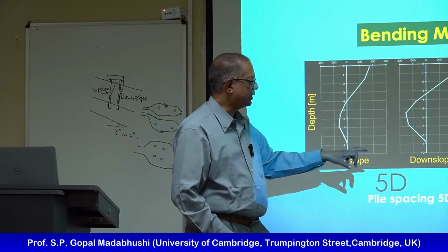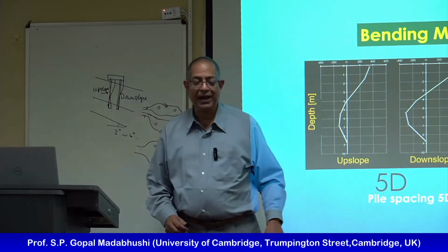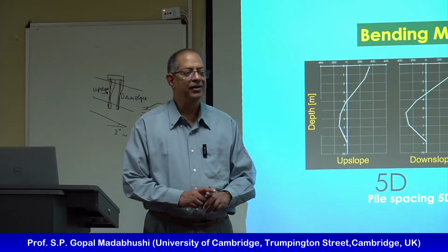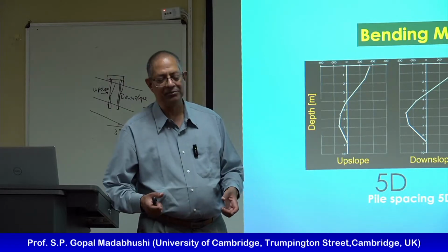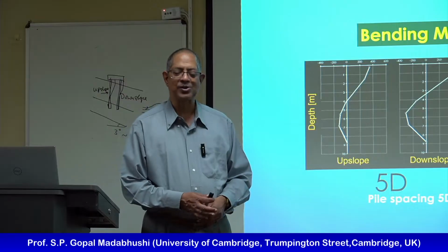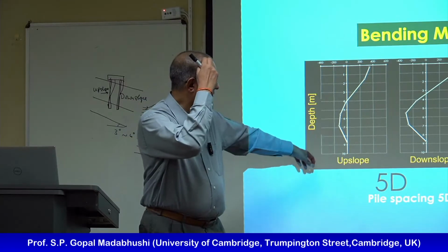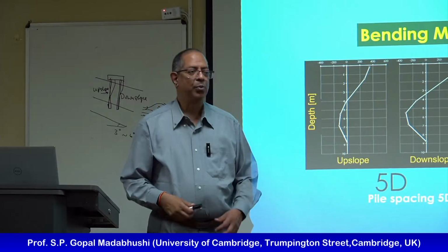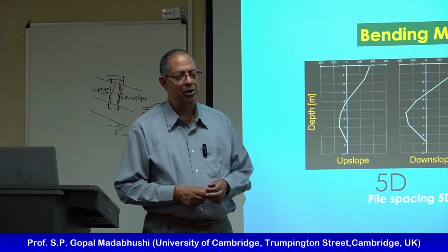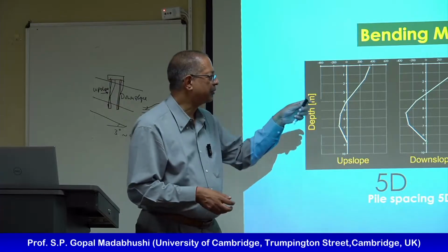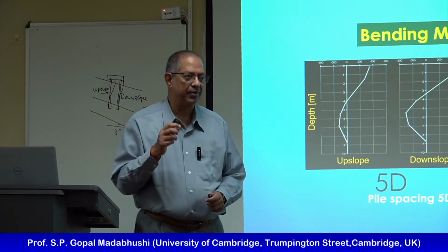So closely spaced piles will act as one large diameter pile. Great, but they also are vulnerable to rotation. Whereas widely spaced piles more or less act as individual piles. This type of thing doesn't happen in static loading.